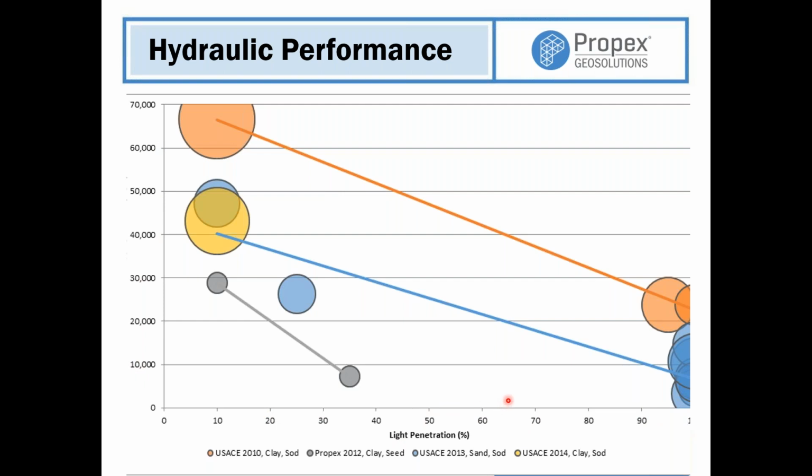We'll talk more about these index properties in the next webinar. But we're seeing very, very strong correlation between the percent open area of these TRMs and the ability of them to provide protection in a very turbulent, high energy condition, which per our design tools allows us to make that same interpolation back to more tranquil flow conditions.